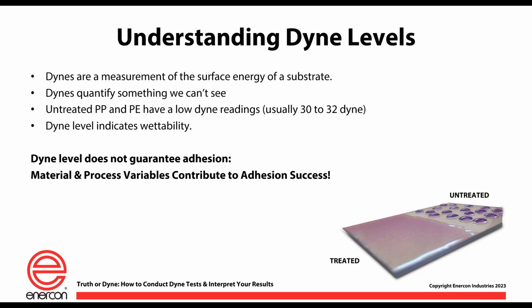However, we're making an assumption here that the dyne number and the adhesion value are connected. And really, the two measurements are not the same. Now, it's great that they match and that we can go forward, make good product, and move it on to our customer. But it is the difference between those two things, and it's a difference that many people just don't understand. So there are times when you can get a high dyne value, and yet the resultant adhesion value is not acceptable. This happens on a regular basis. Hopefully it doesn't happen to you guys out in the audience, but it does happen. And so there is not an exact science here between those two understandings.